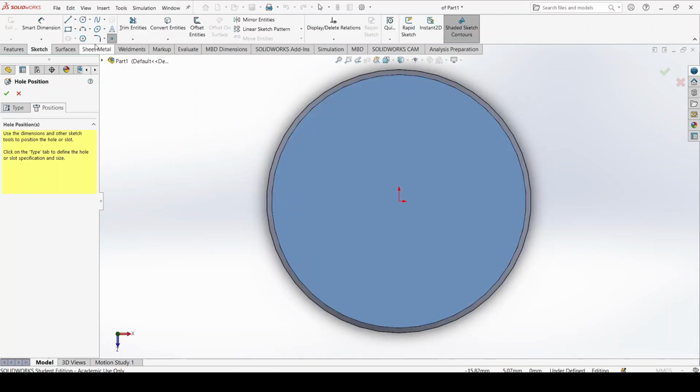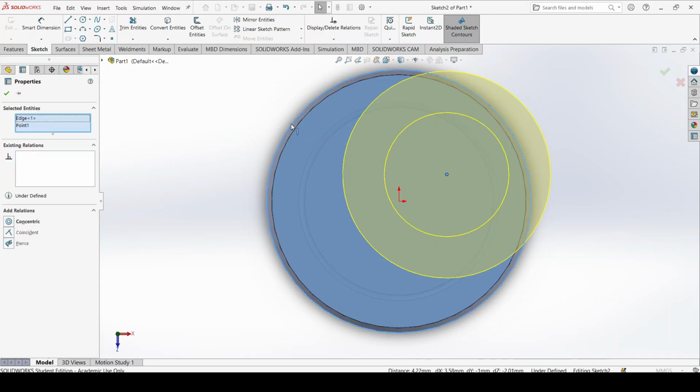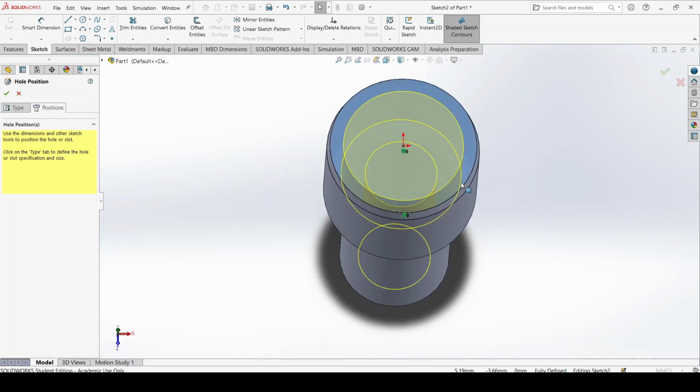And all of a sudden, as you can see, the point is selected as a tool. And I could just put in a point somewhere. I will add it somewhere here. And since there's a center line going straight through the thread, we can deduct that it's supposed to be in the middle. So I will push the point itself, and I will press down Control, and I will say it should be concentric, and thus it gets transported straight into the middle, and this is what we want. So we have a location for our drill.